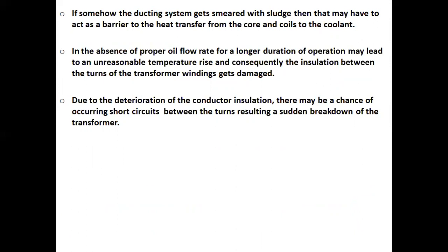In the absence of proper oil flow rate, for a longer duration of operation, it may lead to an unreasonable temperature rise and consequently the insulation between the turns of the transformer windings gets damaged. Due to deterioration of the conductor insulation, there may be a chance of short circuits between the turns, resulting in a sudden breakdown of the transformer.